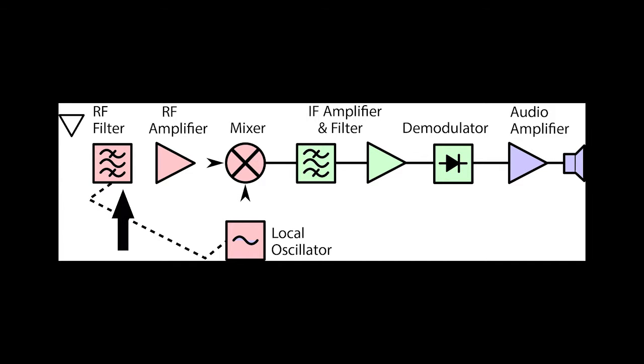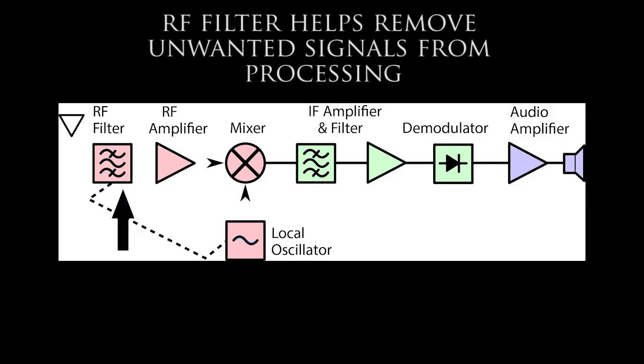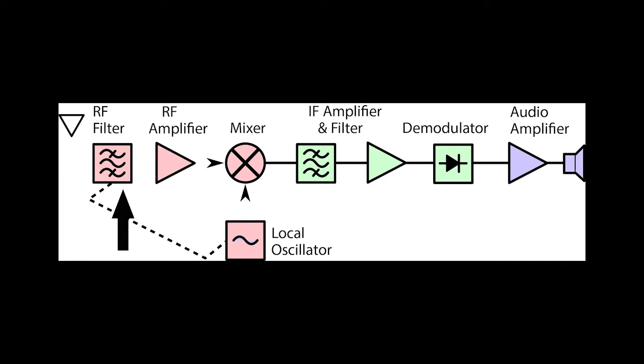Then comes the RF filter and amplifier. The role of the RF filter can be divided into two parts. The signals present in the transmission medium form a very broad spectrum. So firstly, the RF filter rejects the other signals and gives a relatively small spectrum with approximate bandwidth equal to twice the intermediate frequency around the desired or resonant frequency, or in layman's terms, it tunes the signal a little. The selectivity here is not very high. The role played by the RF amplifier is to amplify the received weak signals for further processing, and it is designed in such a way as to minimize the noise amplification.